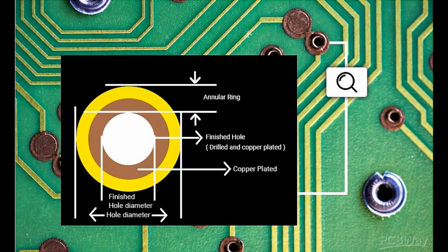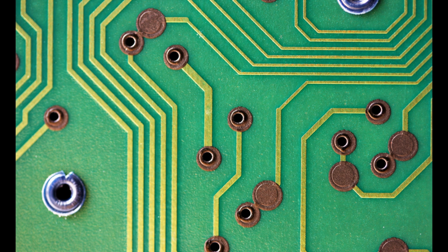Design considerations: the size, shape, and spacing of pads are important for ensuring proper component attachment and soldering. The design must consider the component's package type and lead configuration. Both traces and pads are designed and laid out using PCB design software, and their arrangement on the PCB is critical for the circuit's functionality and reliability. Careful consideration of trace widths, pad sizes, and spacing, along with adherence to design rules and standards, is essential to ensure that the PCB functions as intended and can be manufactured and assembled correctly.